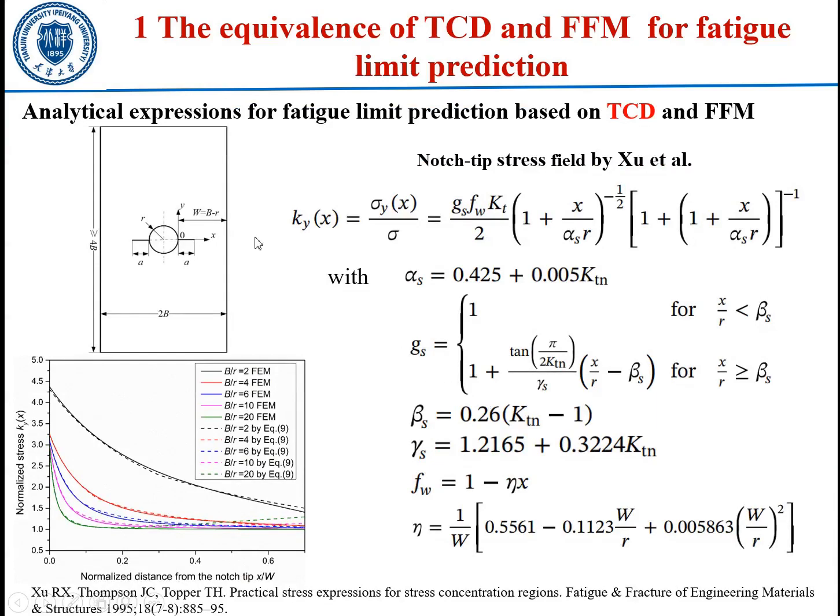To obtain the analytical expressions based on TCD and FFM, we should first know the expressions of the stress field. We compared some existing expressions in the literature and found that the expression proposed by Xu is the most accurate. The parameters in this equation are related to the stress concentration factor, which can be easily obtained from the handbooks. And this figure shows the consistency of the stress field calculated by this equation and that calculated by FEM.